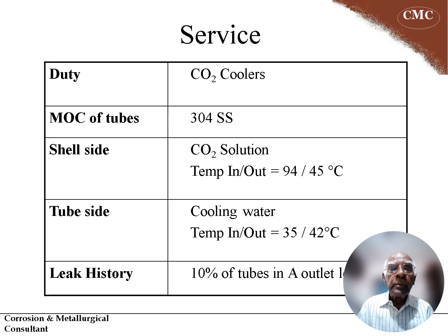So this is a service. This is for CO2 coolers. The material is standard 304 stainless steel, which is a common stainless steel, very often used. The shell side is a CO2 solution, which needs to be cooled from 94 to 45 degrees centigrade, and this cooling is effected by running cooling water on the tube side.